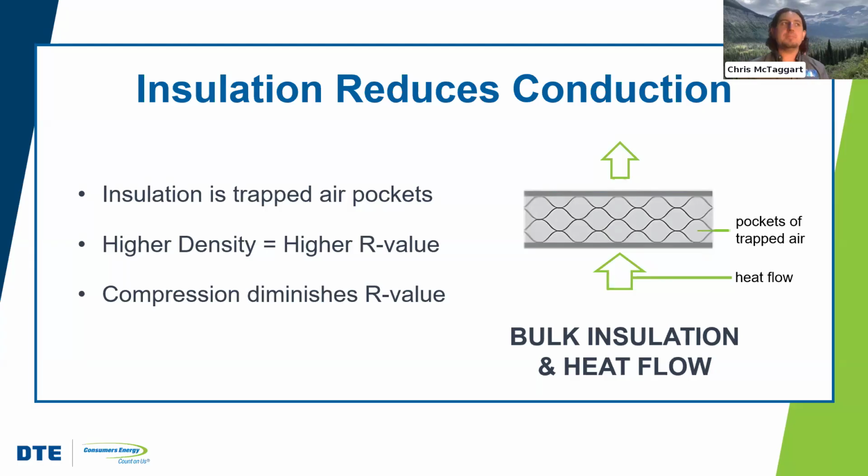Let's take a fiberglass bat. Well, with a fiberglass bat, you don't want to go and compress it, smush it into itself. Why? Because those specifically designed, engineered pockets of air are trapped in the insulation. When you compress it, now you just have the fibers in touch with each other, and therefore it actually promotes more heat loss.